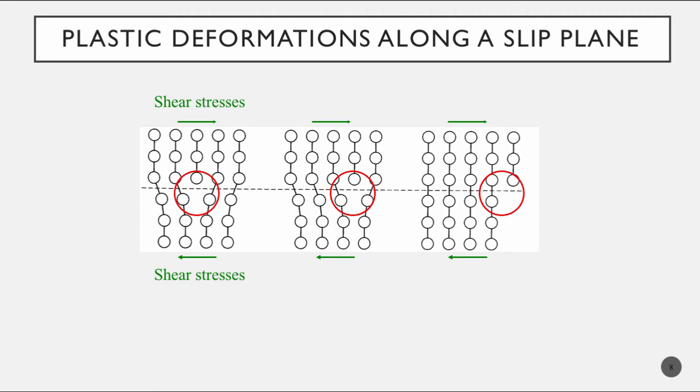The different lines that aren't connected are looking for someone to align with, and so as we move from left to right, the line that's missing a lower neighbor, a lower unit cell, will try to connect and try to connect. And this will just keep sliding and keep sliding until there's nothing left to connect to, because you've hit some sort of additional flaw that stops the slip from going on, that stops you from having something to connect to.